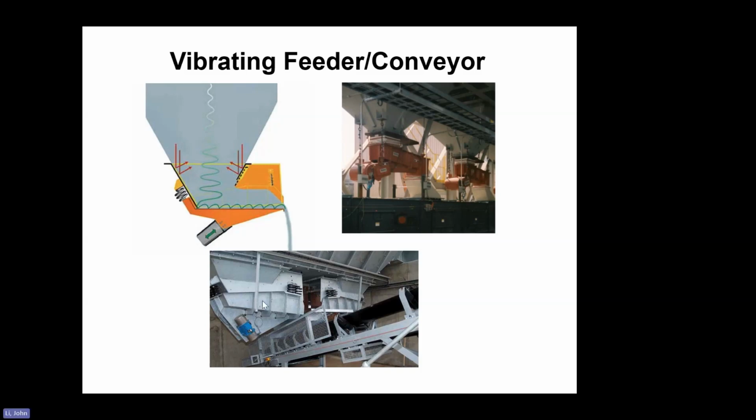Which part is the drive part? The drive part is here or here. Oh, just a vibrating motor. Yeah, very simple. But usually it is controlled by a VFD, so it can adjust the vibrating frequency, to adjust the feeding rate.